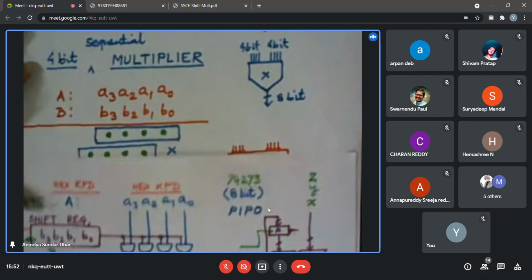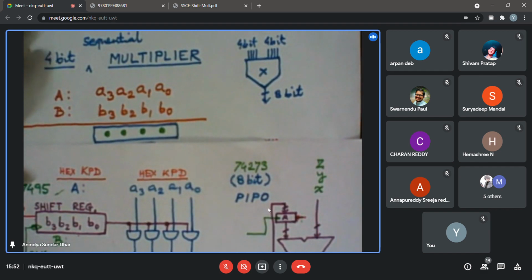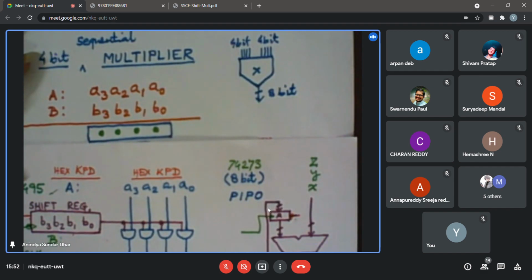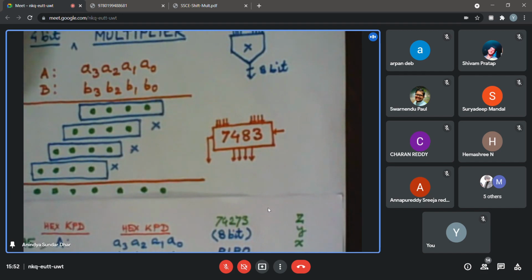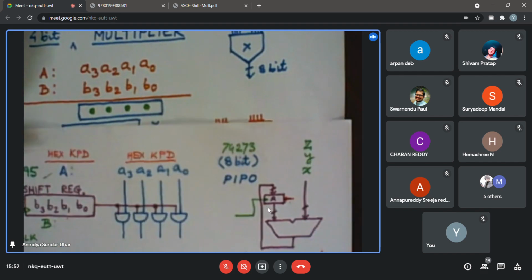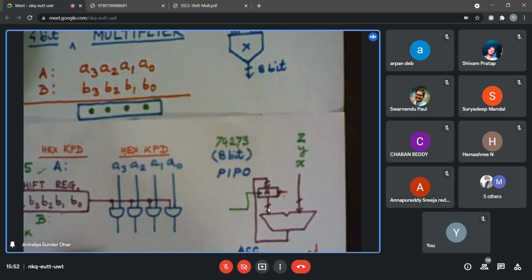So you need to check at each and every clock cycle whether the register contains your expected value or not. Otherwise, you may miss out, and finally you will find the result is not coming. Debugging will become difficult. So you follow single step, use a pulsar, or... So how do we do that? Like a single pulse?